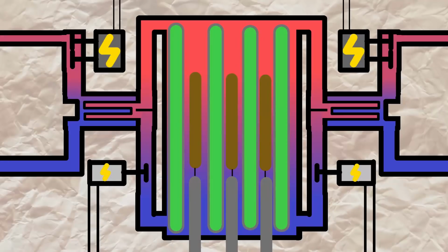But if there is a failure in the national grid and the other 3 reactors are offline, it could be possible for the cooling pumps to stop, and that would result in a meltdown. In the event of a power loss, the reactor would be shut down as soon as possible. But of course, during the shutdown, you still need water in the core. There were diesel backup generators, but they needed a bit of time to spin up. So they needed to bridge the gap between the grid going offline and the backup generator going online.